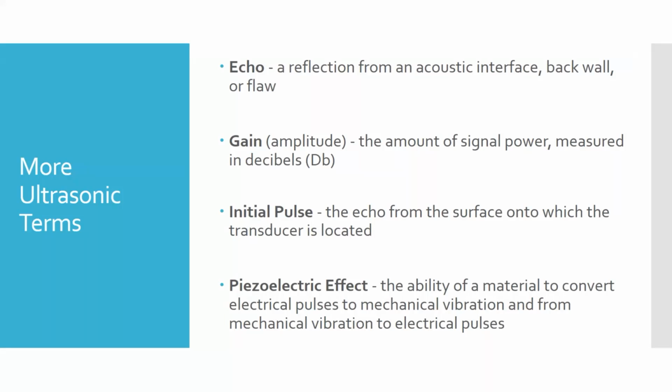Okay? And so almost all the probes we have use a single piezoelectric crystal. And we send pulses to them, 100,000 times a second. That crystal basically vibrates 100,000 times a second. At the same time, when those pulses hit something and come back, they're going to bounce against that same membrane, same crystal, and it's going to send electrical pulses back the other direction. That's one way to do it.